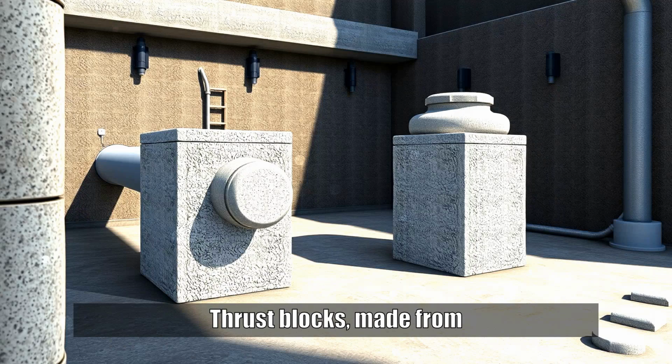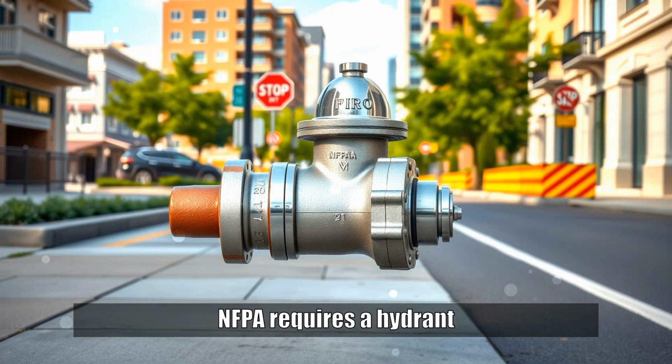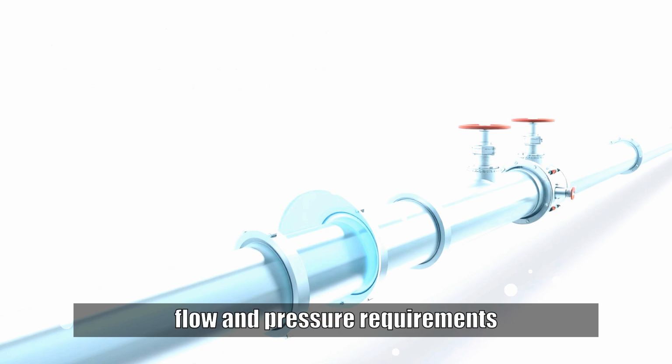Thrust blocks, made from concrete, are installed at every change in direction, T, or hydrant base to resist the reaction forces of pressurized water. Another critical aspect is pipe sizing and hydraulic calculation. NFPA requires a hydrant to deliver a minimum of 250 to 1,000 gallons per minute (GPM), depending on the occupancy and risk. The pipe diameter, usually between 150 mm to 250 mm, is selected to ensure that even the most remote hydrant in the system meets flow and pressure requirements.